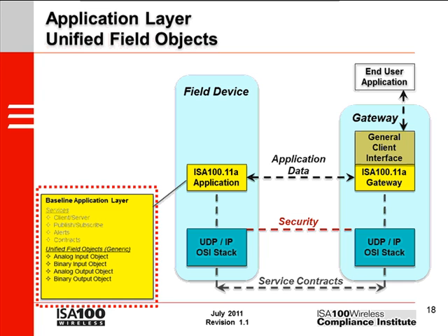The 32-bit data uses exactly the same units as Foundation Field Bus. For example, unit code 1001 is degrees Celsius in both Foundation Field Bus and ISA100. About 700 different units are defined, allowing for a lot of flexibility. For example, unit code 1634 is barrels of US beer per second in both ISA100 and in Foundation Field Bus.